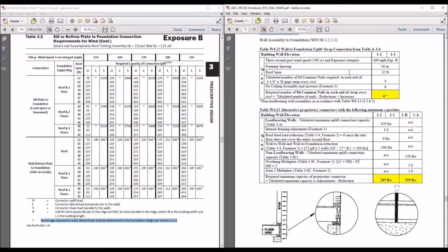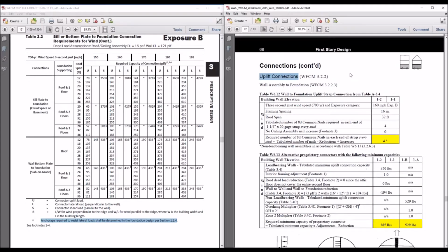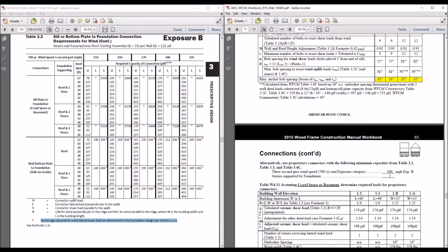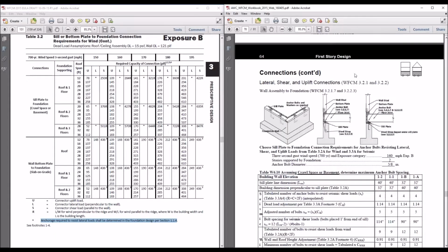Now, let's go back up to one of the pictures here at the top of page 64. Look at this middle diagram here at the top of the page. If you took your straps from the walls all the way down into the foundation system, like we show at this middle diagram, rather than wrapping it underneath the bottom of the sill plate, then you're done.